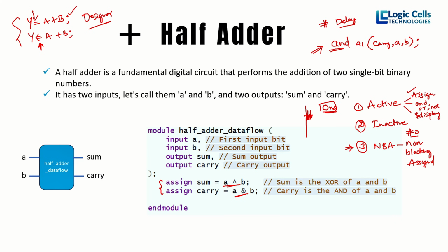Do you know that as an alternative to $display we have $monitor also? In the fourth region, the monitor region, we execute $monitor things. We predominantly use $display and $monitor in our test benches. $display will execute in the active region itself, but $monitor will execute last. It will keep on checking the change in the inputs and outputs, and it will display. Let's look at all these in some examples later.